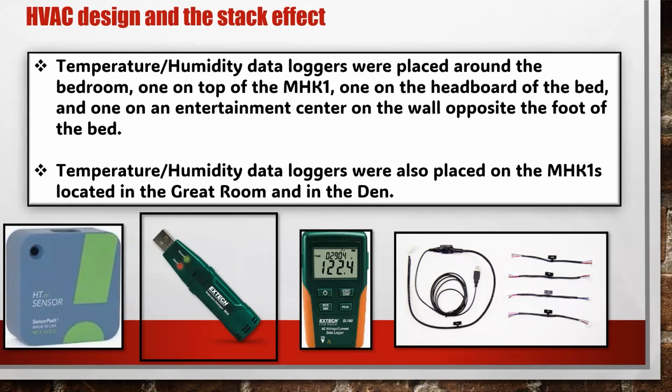Yeah. And now in the new 2023 version of ACCA's Manual S for equipment selection, they say that you can size your unit on its turn down ratio as 80% of the total load, which in a multi-zone unit is going to allow you basically to oversize it to 120% or 125%, no more.